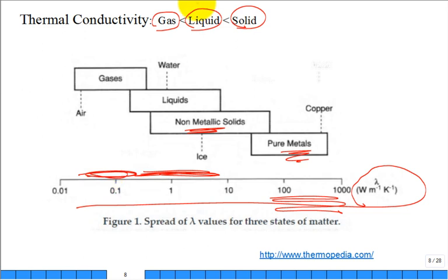Sometimes with a plot like this, it's helpful to ask, what's the lower bound and upper bound? Somebody says, oh, I have this gas, and the thermal conductivity is coming in at 0.001 watt per meter degree C. I'd probably tell them, go look for an error somewhere, because this seems to be outside of the range that seems plausible for your gas.